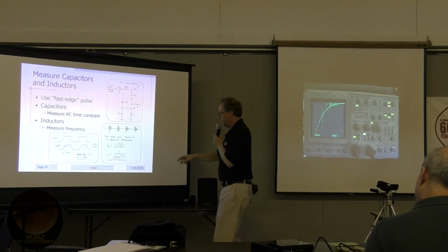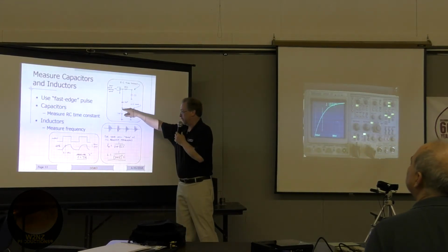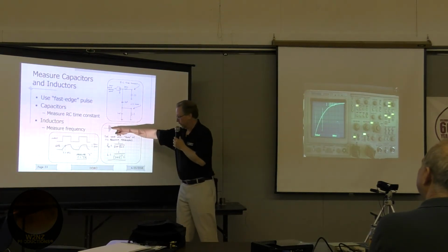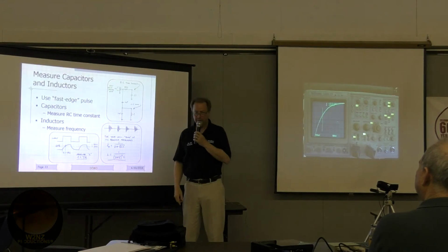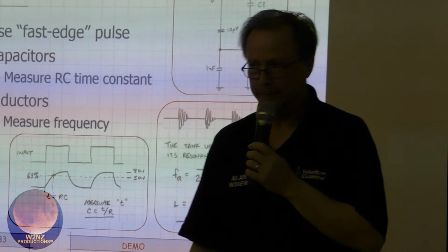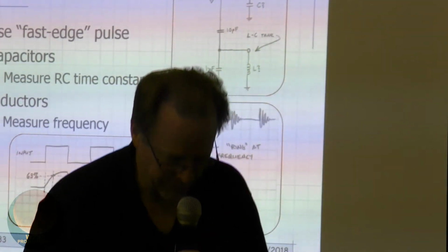Okay? And I'm going to whack this parallel combination of a known capacitor with my unknown inductor. And then we'll see a little ringing that we get. If we measure that ringing frequency, we can calculate the inductance from that. So let's actually set that up over here.